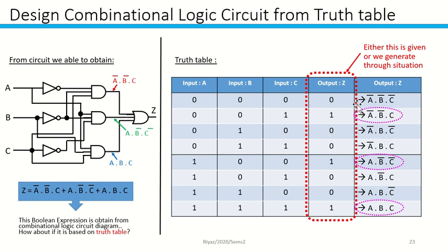So it's depending on the output over here. For example, we will select the output 1 over here, where 0 0 1 becomes 1, 1 0 0 becomes 1, and 1 1 1 becomes 1. Why I select this one is because this is A bar, this is B bar, and C. So this is equal to this one. So that's why we select 1 over here.